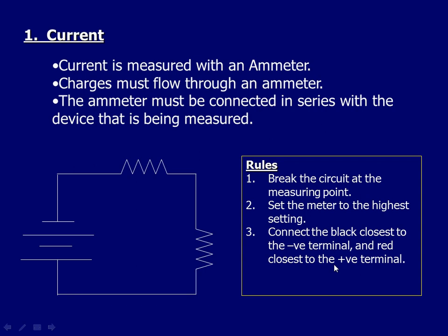I'm not quite to the 20. Wait a minute. Oh, no, sorry. I'm at about 150 on this. Can I go to the 50 scale if I'm at 150? The answer is no, because the maximum is 50 on that next scale. And if I'm at 150, I'm going to blow it over the top. So I stop there. I make my measurement, and I have my current.